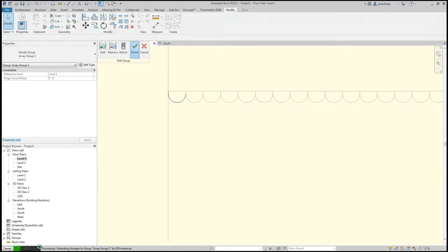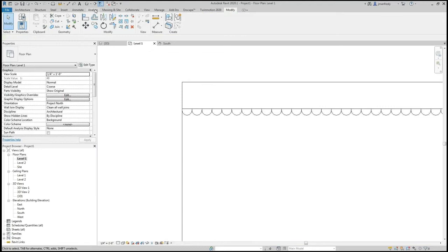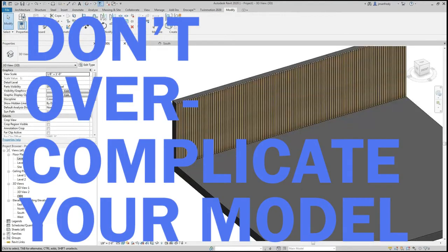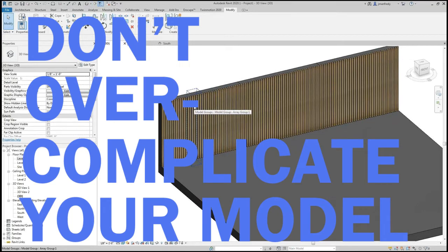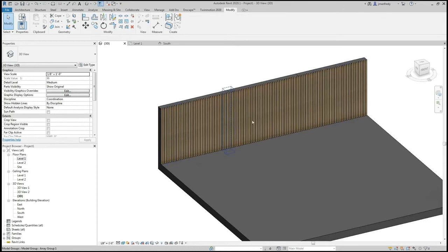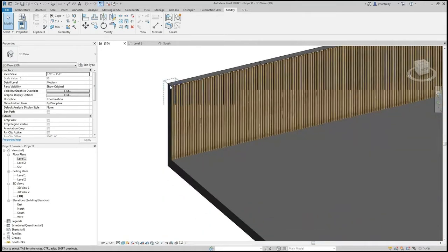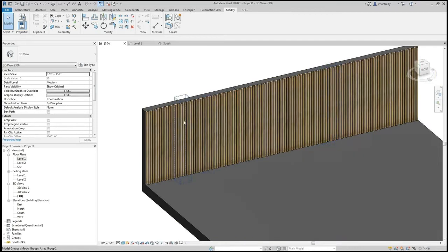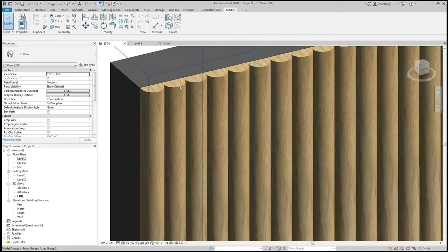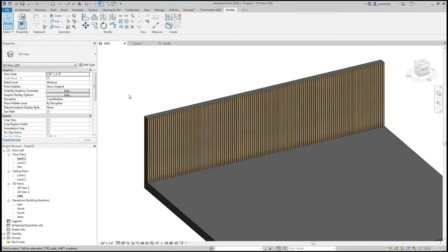And you'll see here it's taken up quite a bit of time to update the array because these type of modeling exercises tend to overcomplicate Revit. So this is not something I would necessarily suggest on any project. Although if it's a smaller project, you can probably get away with it. But as projects get bigger and bigger, these types of options, especially when you have curvilinear objects like this, dramatically add to your file size and the user experience. So I limit how often I do this type of work in Revit to speed things up while I'm using the software.